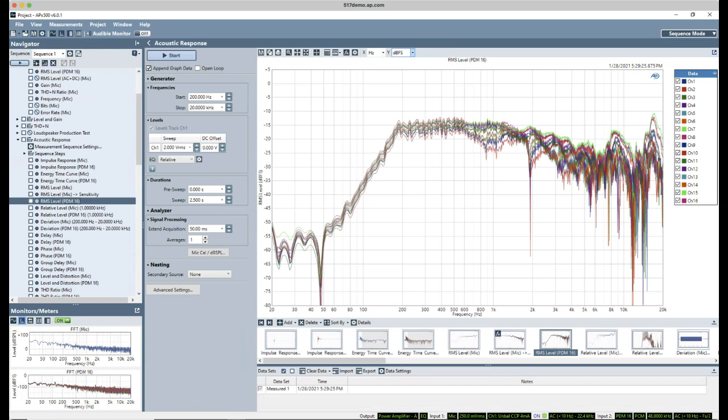If we have a microphone and it has some kind of cavity, and that cavity is typically sealed from the rest of the device, if that seal fails, effectively the cavity size will change, and the volume of the cavity will give you a resonant frequency, and you'll have a peak in your frequency response corresponding to that.